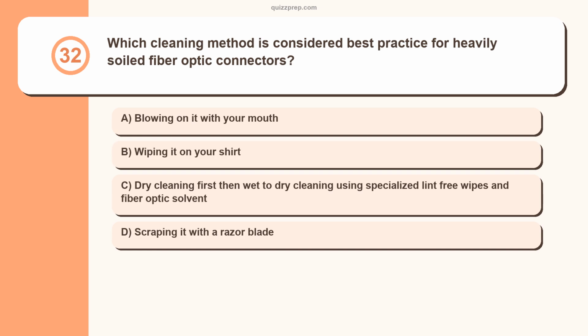Question 32. Which cleaning method is considered best practice for heavily soiled fiber optic connectors? Blowing on it with your mouth, wiping it on your shirt. Dry cleaning first, then wet to dry cleaning using specialized lint-free wipes and fiber optic solvent, scraping it with a razor blade.